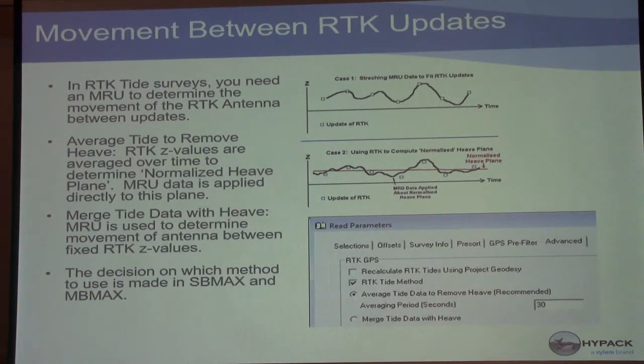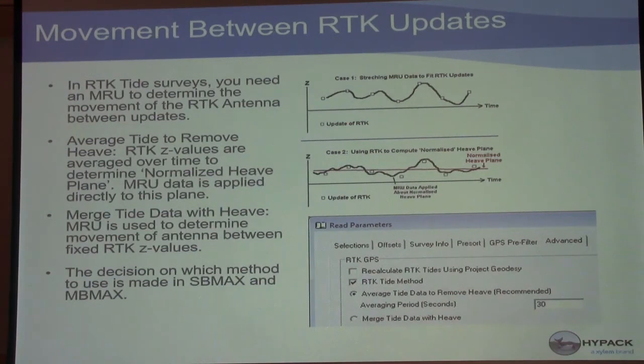So you're pretty much making the assumption that you have a motion sensor. Okay, so if you're still using a GPS that's outputting a 1 second update, you should be using a motion sensor. You can basically use the RTK as a motion sensor if you're outputting 10, 20 hertz, or in the case of a POS, 50, 100, 200 hertz or so. And it's going to give you a pretty good idea. Basically you're going to use that value instead of smoothing out the values for water level.